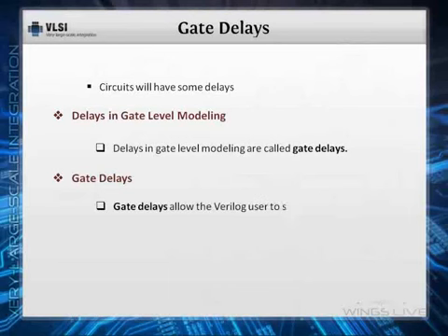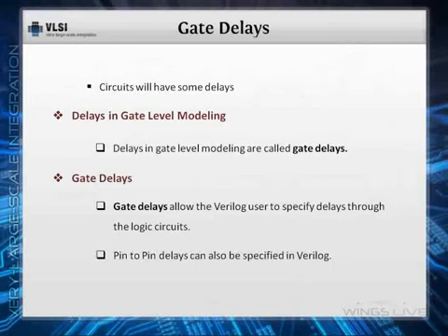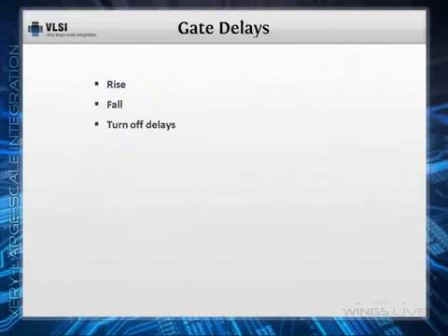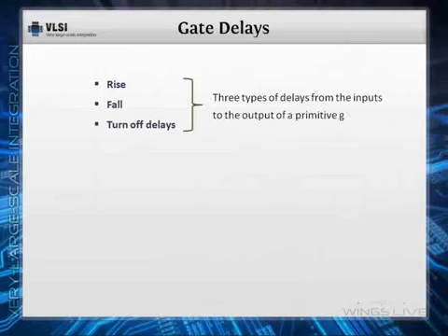Gate delays allow the Verilog user to specify delays through the logic circuits. Pin-to-pin delays can also be specified in Verilog. They are discussed in our upcoming chapters. Let's start a discussion about gate delays with rise, fall, and turn-off delays. These are the three types of delays from the inputs to the output of a primitive gate. Let's discuss these one by one, shall we?